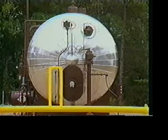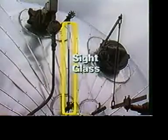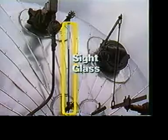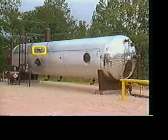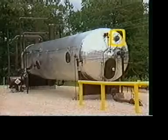Sight glasses are the best way for a pumper to see if the treater is doing its job. Should the sight glass break, a safety feature of the sight glass valve will cause a steel ball to seat and shut off the flow. The low-level controller ensures that the fire tube is always covered with liquid. It's designed to shut down the burner if liquid falls below the desired level. Shutting down the burner keeps the fire tube from overheating, which would result in tube failure and a safety hazard.